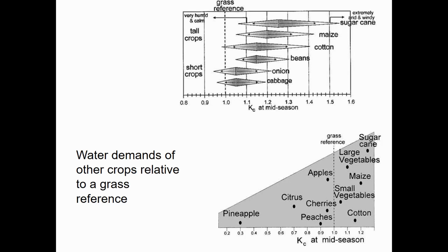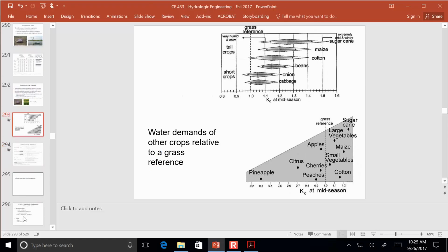All right, so what we're working towards is an idea of a water balance where we have to account for the entire water cycle: the increase in soil moisture when it rains, the transport down to the saturated zone, the movement of groundwater through the saturated zone, the relative fraction of runoff that's leading to flow in streams, and so on. Evapotranspiration is usually considered a pretty minor factor in the overall water balance. It's a major factor for those who are growing the crops, but that's all we have for today as far as evaporation.